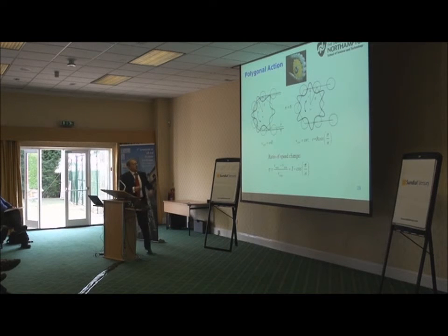Okay, how do we deal with this? Here's a very simple calculation which can be done. When we have a polygon, we can draw this polygon, in this case when we have 6 teeth on the sprocket. We can calculate the maximum value of the chain velocity, which moves in this or the other direction, by knowing the rotational speed of the pulley.